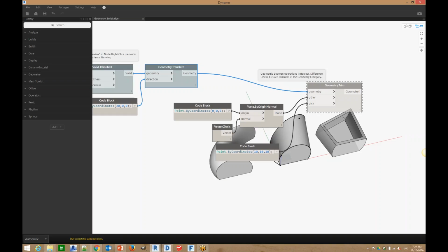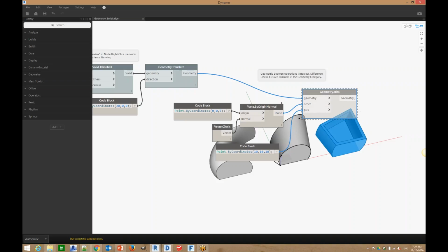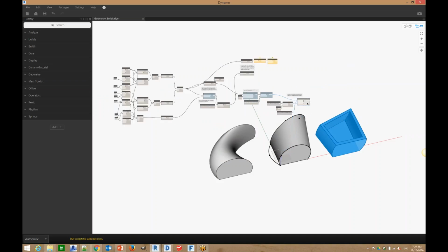You can freeze Revit nodes so that while you're making your changes in the graph, it's not actually updating your Revit. People used to be just unplugging and replugging nodes. So freeze now has a different visual aspect, so it's easier to read which things are frozen, which things the preview is off, and which ones are operating on a regular basis.